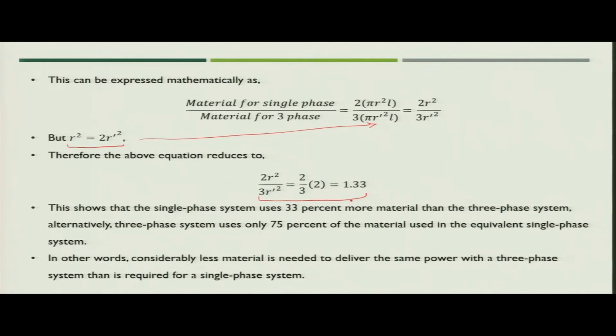So, what can you observe now? You can observe that the single phase system will use 33% more material than the 3 phase system to supply the same amount of power and to incur the same loss in the transmission system.